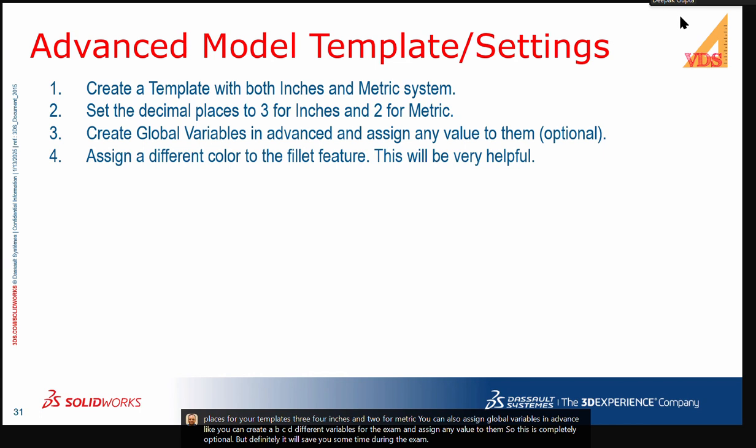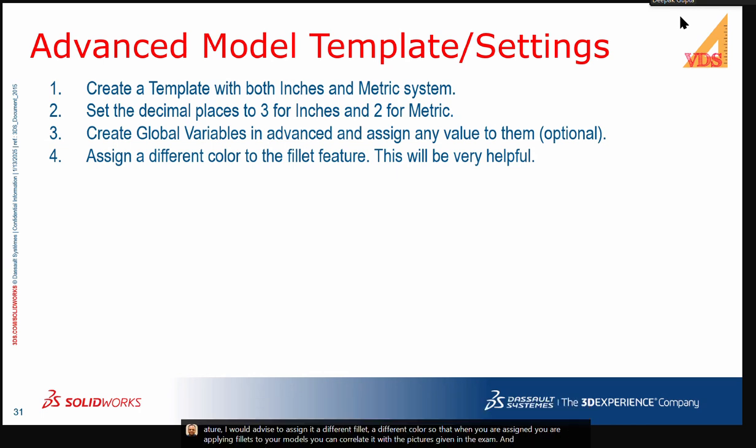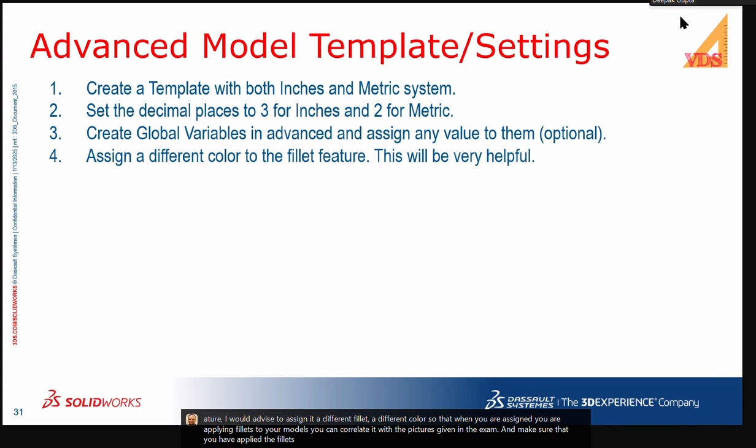Usually, we do not assign colors to different features, though it's always helpful to have different colors for the features so that we can simply recognize them. But specifically for the fillet feature, I would advise to assign a different color, so that when you are applying fillets to your models, you can correlate it with the pictures given in the exam and make sure that you have applied the fillets on the desired location and you have also put in the correct values.